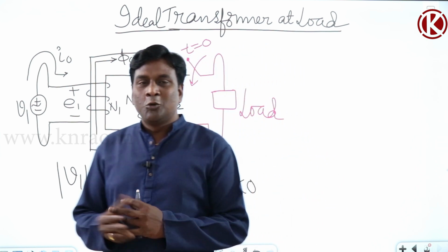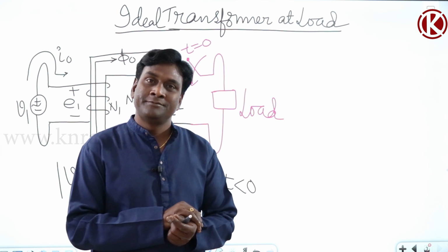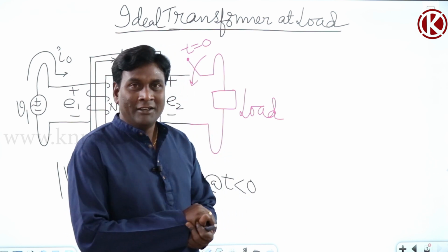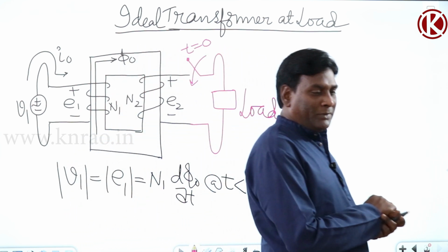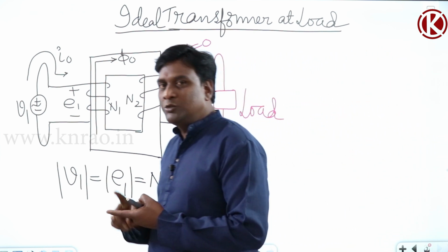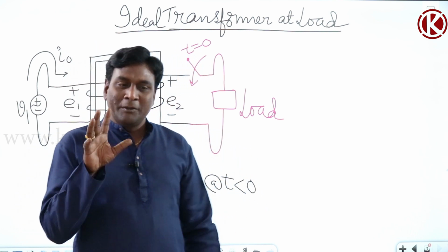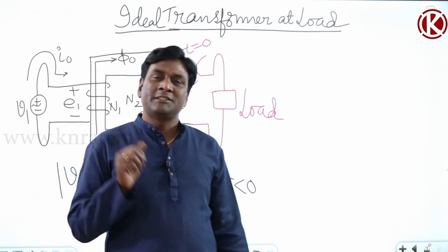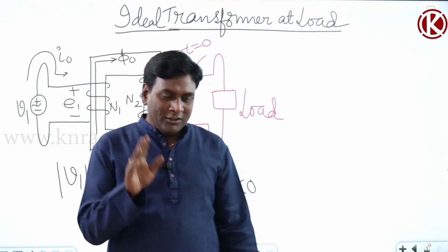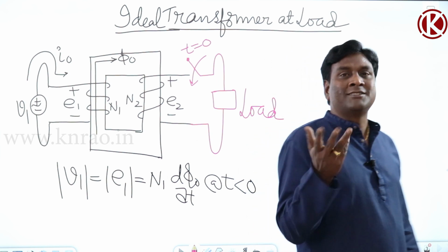If you say it is to reduce eddy current losses, that may not be right, may be wrong. Basically, laminations we do to reduce eddy current losses in machines, because in machines steady state behavior is important. Let me give you a small example.